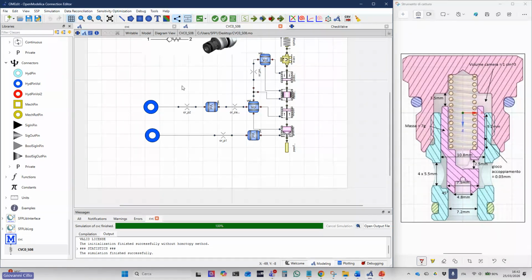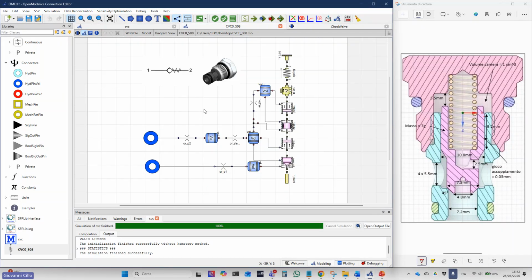But the most important is the damping by the fluid. Also how much air is in the fluid, and the bulk modulus of the fluid. So there are many parameters that can influence the transient response. If you know them, you also have to consider the trend of your results more than the specific number.